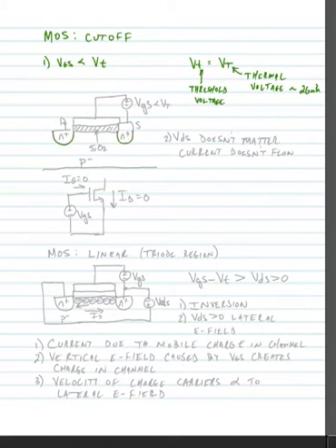So for our MOS device, we'll look at our cross-section, and we'll just draw a simple cross-section. So here we have an NMOS device where we'll start with a P- substrate material. We'll have two N+ regions that will define the source and the drain. And then we'll have our gate contact, which is separated from the channel by silicon dioxide, or an oxide layer in the generic case.